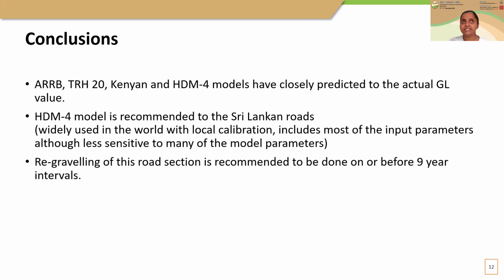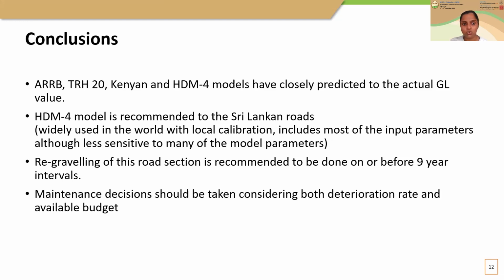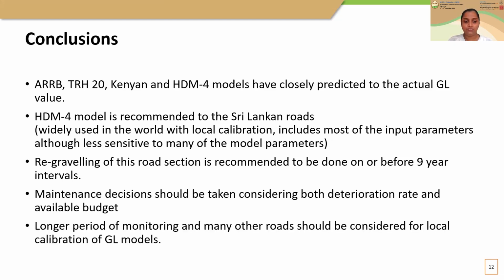Regraveling of this road section is recommended to be done at 9-year intervals, even though we should consider the available budget and the timing, and the condition prediction for this type of maintenance decisions. For an accurate local calibration of gravel loss models, it is recommended to have a longer monitoring period and more road sections.